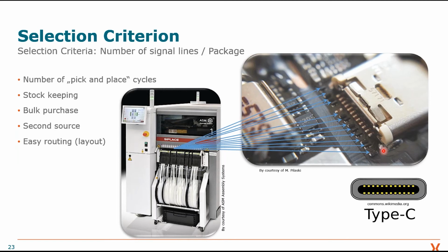And if I have a high-speed bus where I need lower capacitance, in effect, the absolute deviation will be lower as well. So then, maybe on a bus where we use 2 picofarads, now the deviation is only 0.2 picofarads. And this impact is really minor and less critical in real life applications.